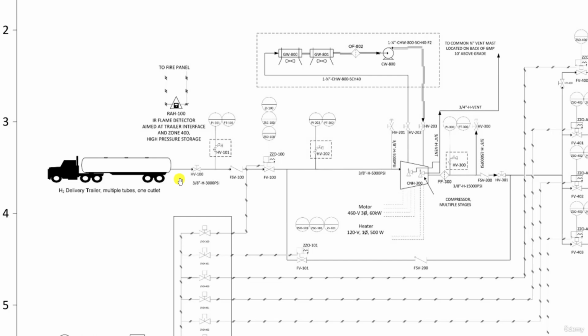Why is that important? Because the fluid being handled here is hydrogen, which is an extremely flammable gas, and we need to know how this connection is ensured so that we know how to handle emergency situations in case of connection failure or loss of containment. This information is not illustrated on this P&ID, but I'm pretty sure there is a separate P&ID that covers this aspect in detail.